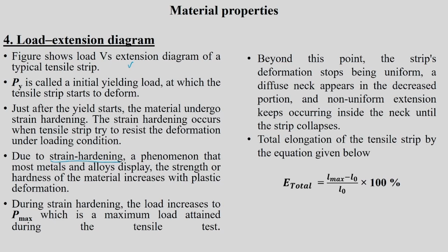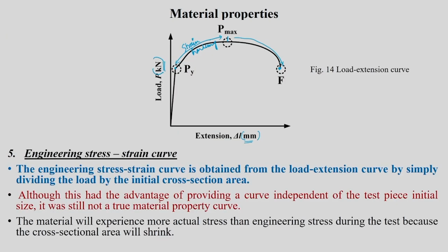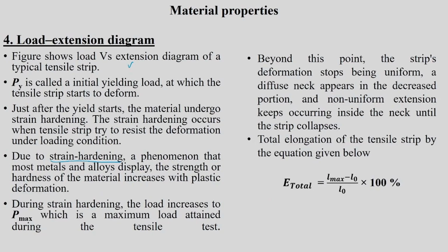Of course, one can understand the mechanism more from a material science point of view, but for this particular course this would be more than sufficient. Okay. So, the load increasing with displacement in the plastically deforming region is mainly because of strain hardening. So, once you cross the strain hardening portion, you will reach a maximum load called P max. Okay. P max is the maximum load, and once P max is reached, something is going to happen. Okay. So, what is that?